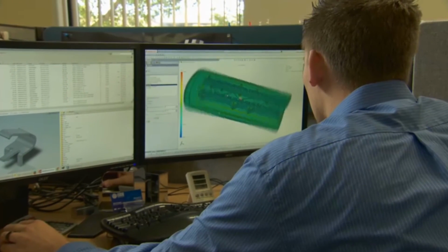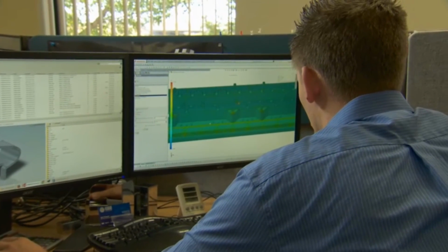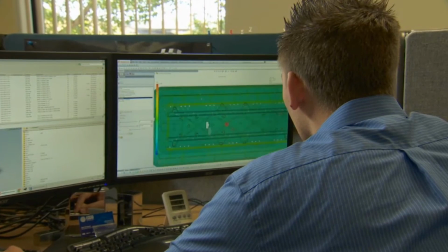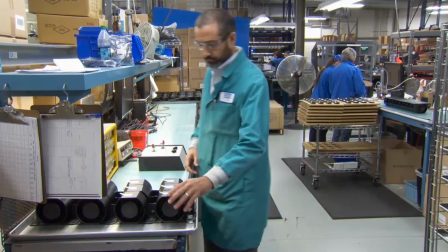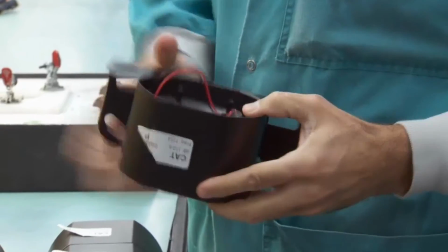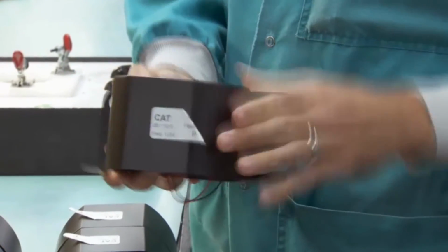So we use Plastics to validate a few different things. One is the design, whether it's manufacturable. We also use it to check features, whether to add or remove or change the dimensions of them. We were able to optimize our design to say, okay, we can make this out of a single part. It can be this thick, the plastic will be strong enough, and the customer wouldn't see any performance degradation, but we can offer this at a lower cost.